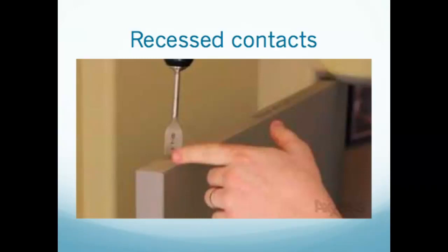So basically, to install one of those, you drill in the top of the wooden door. You put the magnet that has no wiring on it. You sink it right down in there. And then in the door frame, just opposite it, in the top of the door frame, you pull through the wiring and that other magnet, and they touch each other essentially, or they're really close to each other when you close the door. And when the door swings open, the reeds pull apart, and the alarm goes off to tell you somebody has opened that door.